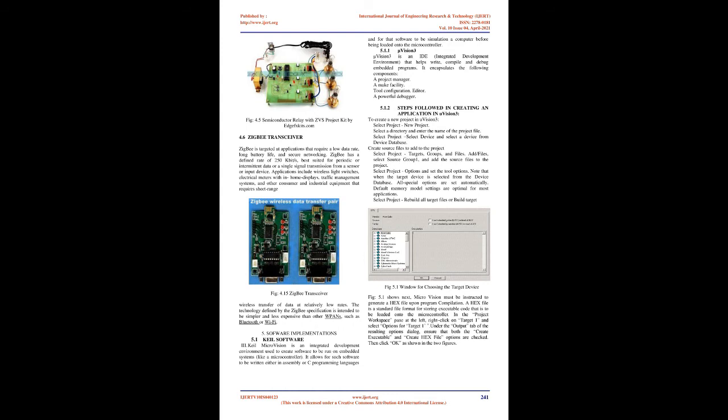The transmitters take input from the controller's serial transmission pin and send the output to RS-232's receiver. The receivers, on the other hand, take input from the transmission pin of the RS-232 serial port and give serial output to the microcontroller's receiver pin. MAX232 needs 4 external capacitors whose value ranges from 1µF to 22µF. Microcontroller. MAX232. RS-232. TX.